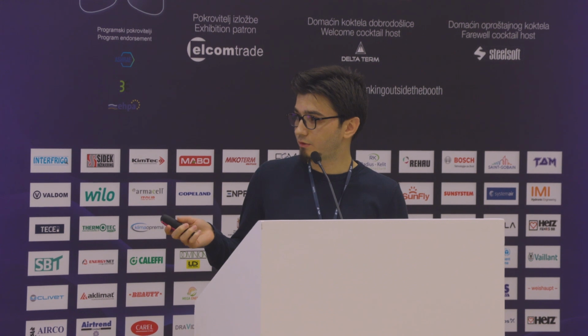The optimum melting temperature is very important for phase change materials, because the main reason that we are using phase change material in the wall is to have its phase changing. Therefore, we can use its latent heat occurring in the phase change. Therefore, it's crucial to find the optimum melting temperature, and the optimum melting temperature depends on many parameters, like the wall orientation and the climate of the region, maybe even the thickness of the PCM used, and the components of the building also.